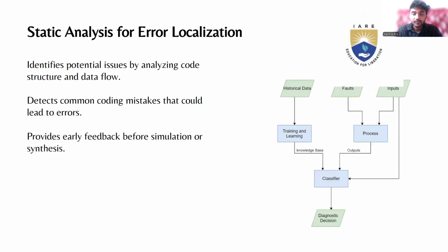Static analysis for error localization. Static analysis looks at the code structure and the data flow. It detects common mistakes early and gives feedback before simulation or synthesis. This helps to catch errors at an earlier stage.